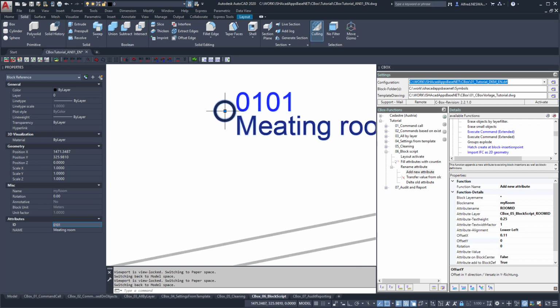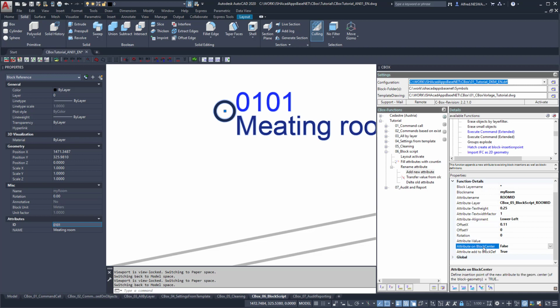So from the insertion position, 0.11 to the left, and we don't want a predefined attribute. We have the choice to position the attribute with the offset values based on the insertion point or based on the geometric center. Both options are available.